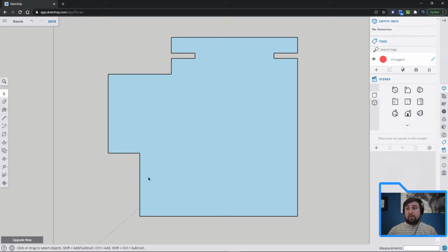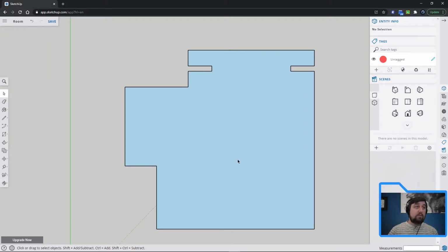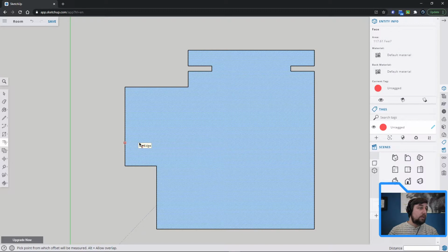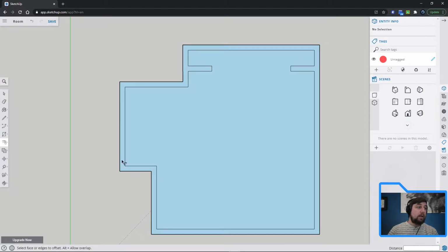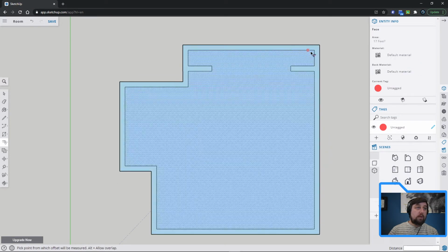First, let's, spacebar, remember, get you back to the regular mouse. First, let's do the offset for our walls so that we have our actual walls. All right, so I'm gonna go into my press pull, and this one down here is offset. Underneath on the options or drop down, whatever you wanna call that, for the wall. So if you click on the inner edge, the actual closed shape, and press and pull this out, you'll see you start making the offset. So I want my offset, I said just before that the offset is 4 inches for the wall thickness. So there you go. I now have a wall all the way around my entire thing. Spacebar, get back, right like that.